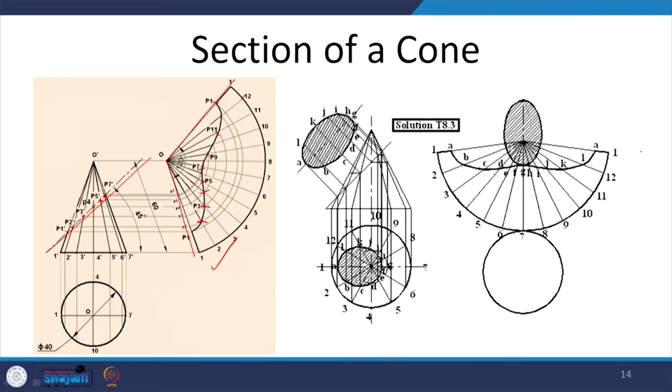But again, what happens to the top surface? If we look at this, we actually will see an ellipse coming here. This is what the conic section is going to be. So for this true ellipse, again we will mark where the smaller and the longer axis of the ellipse is. If it was drawn here, it is this ellipse. If it was drawn here, it would probably be this ellipse, but it will be difficult to make it here because we will not have sufficient sheet, the paper or metal or whatever. So it is put here.